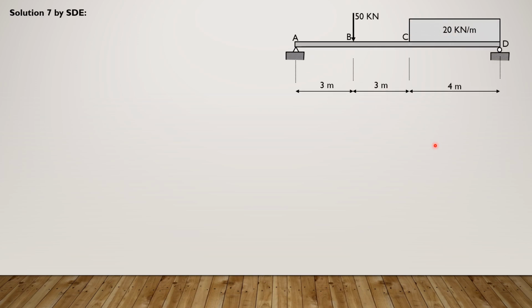So this is the beam, and let's set up everything. Moment BC is 51 times 3, so 153 kilonewton meter. That's moment BC, or B to D. While moment B to A, because this is the other way around, is negative 153 kilonewton meter. Likewise, moment C to D is equal to 51 times 6 minus 50 times 3, which was computed before. But moment C to A is negative 156.